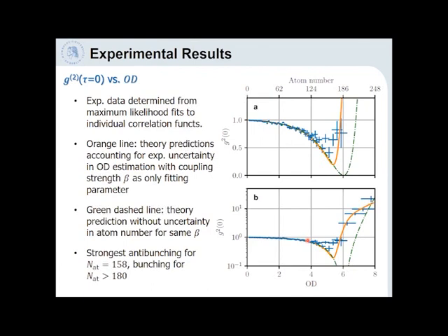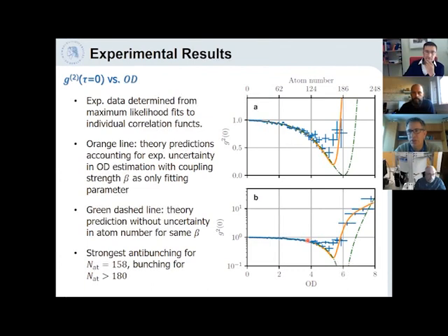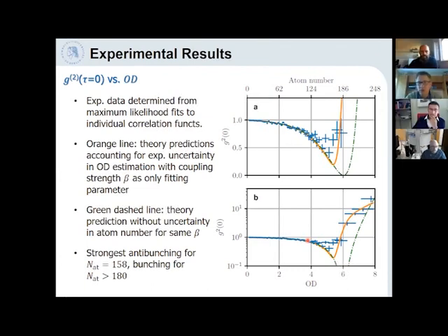So that is over 3 orders of magnitude of reduction of the fiber diameter. We start with a 125 micron diameter fiber, we go down to 125 nanometers, and we meet this 125 nanometers to within plus minus 6 nanometers. And this is just by modeling the process and then doing what the computer calculates has to be done to achieve a certain radius profile of the fiber, and the outcome matches the predicted profile to better than 5%.